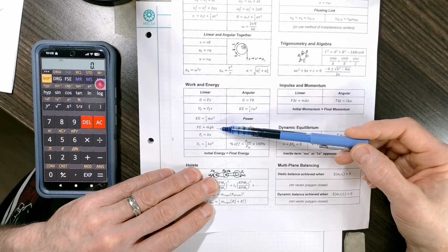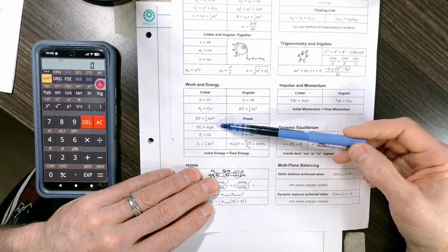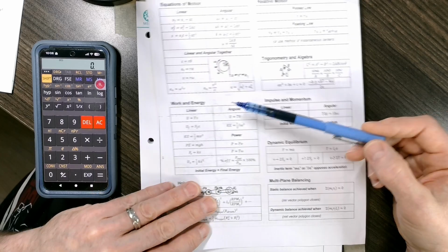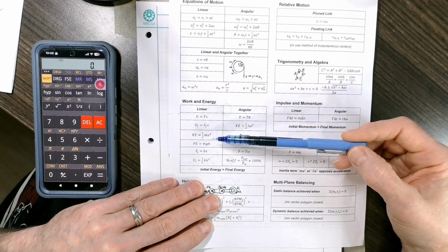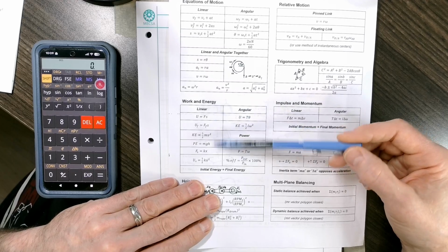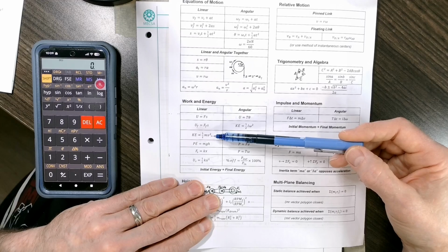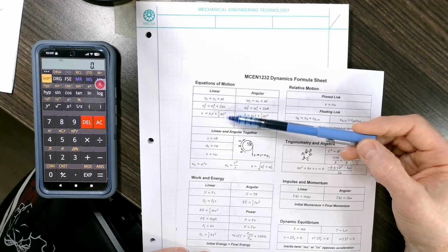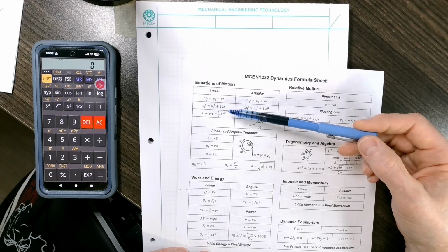And then you say, yeah, I'd sure like to know the time. You don't have to go to the impulse momentum method. You've already applied kinetics. You've applied it in the form of the work energy method. If you need to have time out of this, then take your output from the work and energy method and use the kinematic equation and get your secondary value you want.